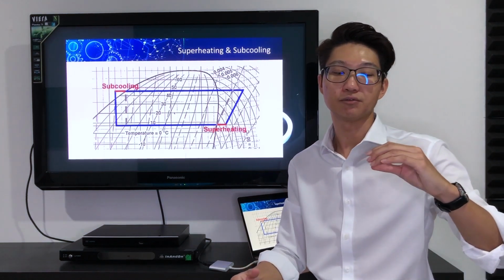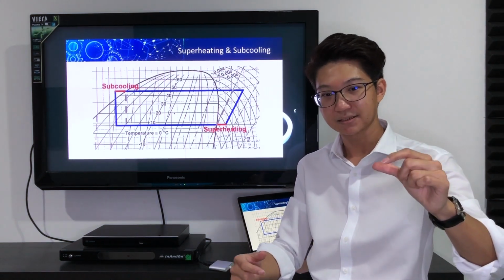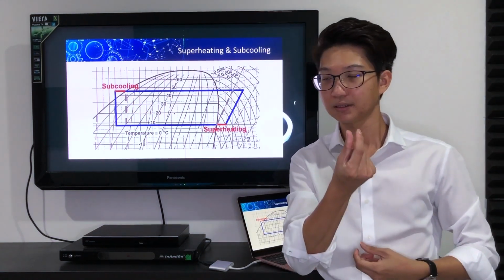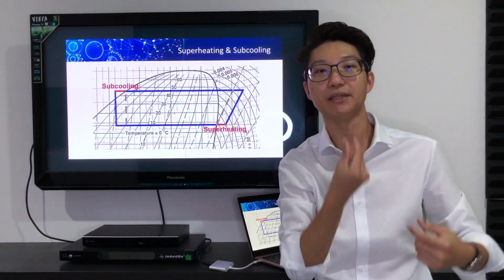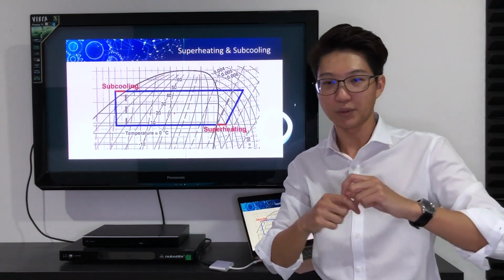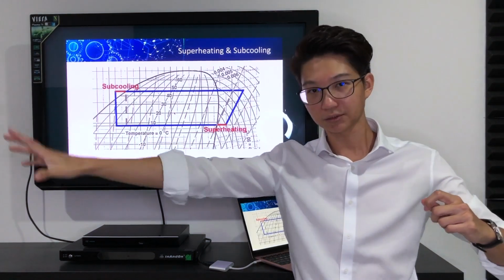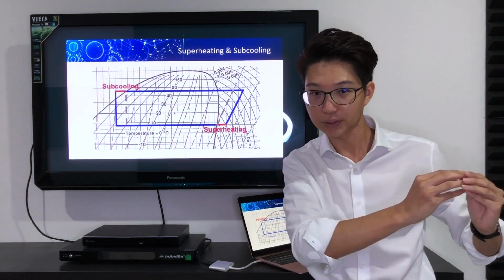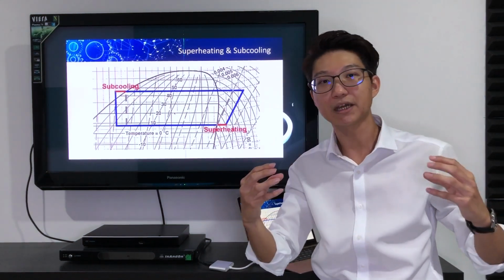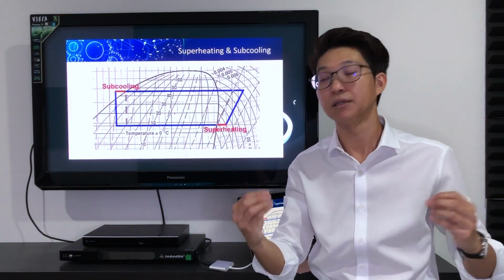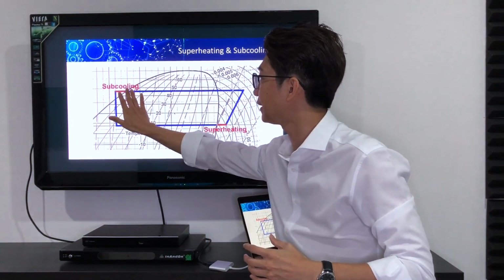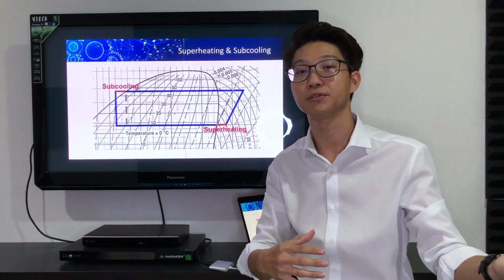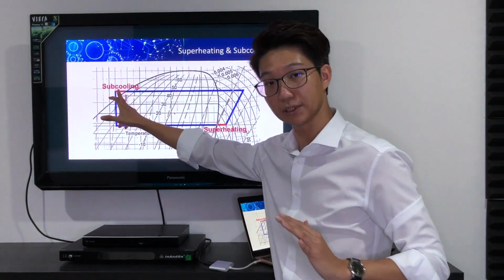You see, when you are left with gas inside the system, that means you are basically absorbing this amount of heat. You bring it outside, you bring back the same heat, right? We don't want that. We want everything thrown outside, then come back in 100% liquid, so that the cooling capacity is maintained. If you don't have 100% condensation, your cooling capacity will reduce, right? That's why we introduce subcooling, right?